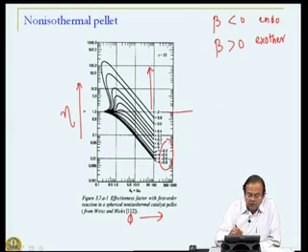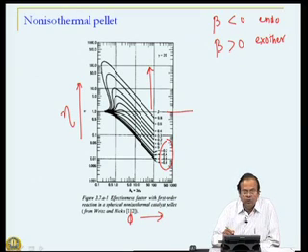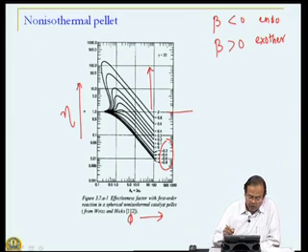So, you have effectiveness factor greater than unity, and the reason, as I just now mentioned, is that conditions inside the pellet, namely temperature being higher than the bulk, ensure that the rate of reaction inside the pellet is higher than that in the bulk, leading to average values also being higher. Now, there is another feature of non-isothermal pellet which is also apparent in this figure, and we will spend some time looking at that behavior.